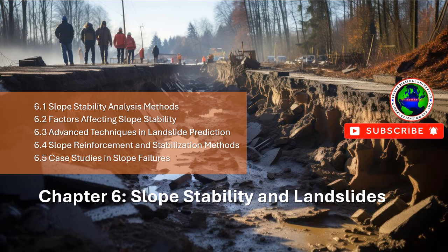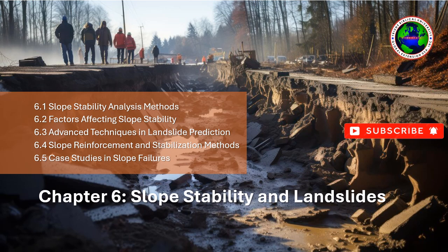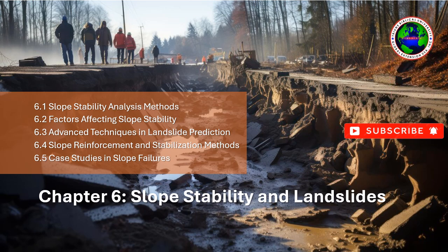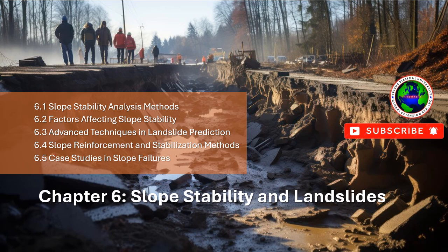FEM is widely used to model the behavior of slopes under various conditions. This method divides the slope into small elements and solves the equations of equilibrium for each element to predict stress, strain, and deformation. FEM can account for nonlinear soil behavior, pore water pressure, and the effect of varying loading conditions, making it ideal for complex slope stability analysis.